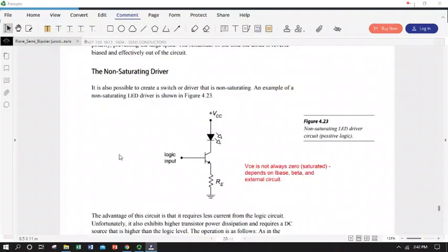And the rest of the examples in this chapter are just more variations on the same, looking at different ways we can apply Kirchhoff's voltage law between collector and emitter, with some previous knowledge about our collector-emitter voltage drop, or using a beta and a knowledge of the base current, usually given to us via a base emitter Kirchhoff's voltage loop and our understanding of the base emitter junction voltage.